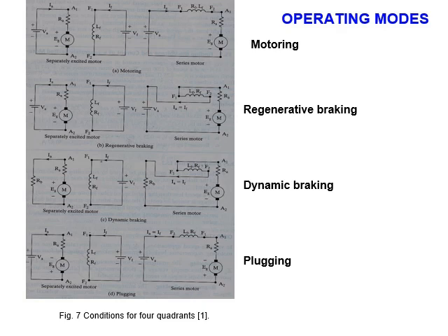The first mode is the normal mode. Power comes from the supply to the armature and the field. This is for the separately excited motor. For the series motor, it comes from the supply to the armature. It's a normal motor. In regenerative braking, what happens is we return the current from the armature back to the supply.